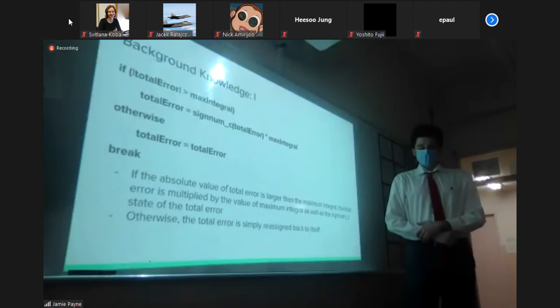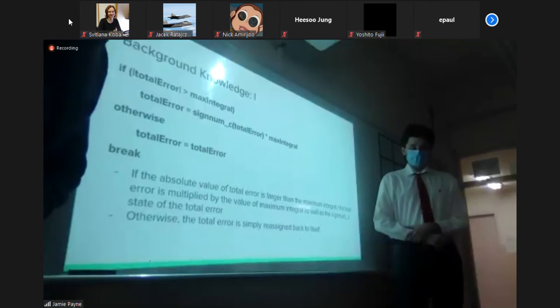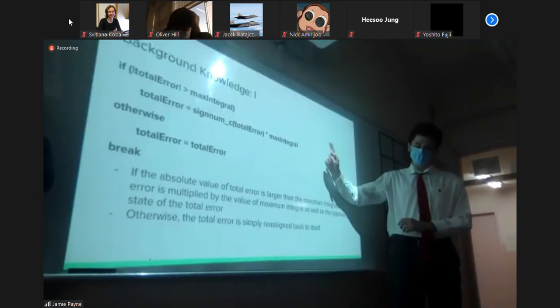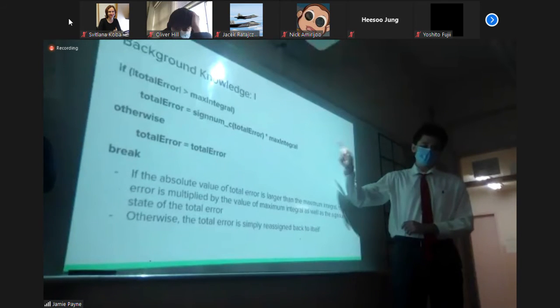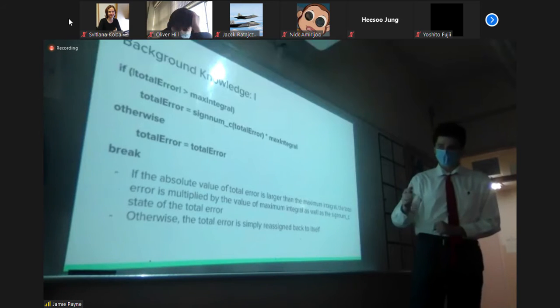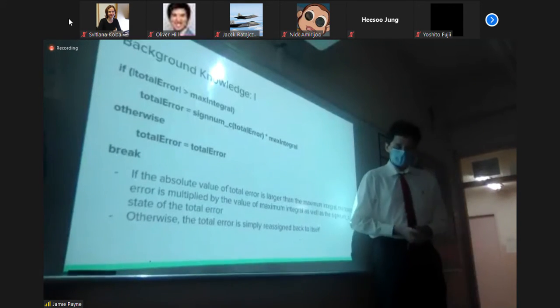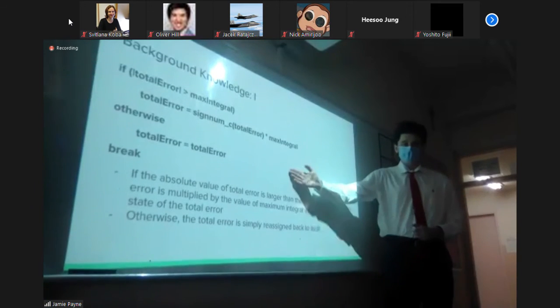Then, if the absolute value of total error is larger than the maximum integral, the total error is set to the maximum integral multiplied by the sign of the total error. If you're confused what sign is, it's right after this. Otherwise, the total error is simply assigned back.